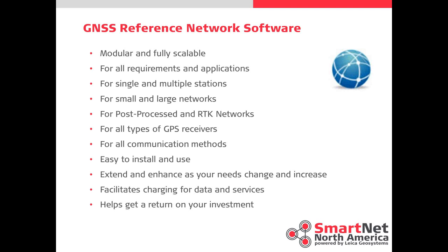It needs to meet requirements for multiple applications, be able to handle us being a very large network, probably one of the largest in the world, be able to handle post-processing, RTK, and be able to take different types of receivers in, be it from legacy receivers back in the 500 days to current GR10 receivers for Leica, or even if the need arises to be able to bring in alternate receivers, Trimble, Topcon, what have you. Of course, it needs to be, for us, easy to install and manage. On a smaller basis, our software is very easy to install and manage. On the scale that we're working at, it is a full-time job, and that's why we're here.